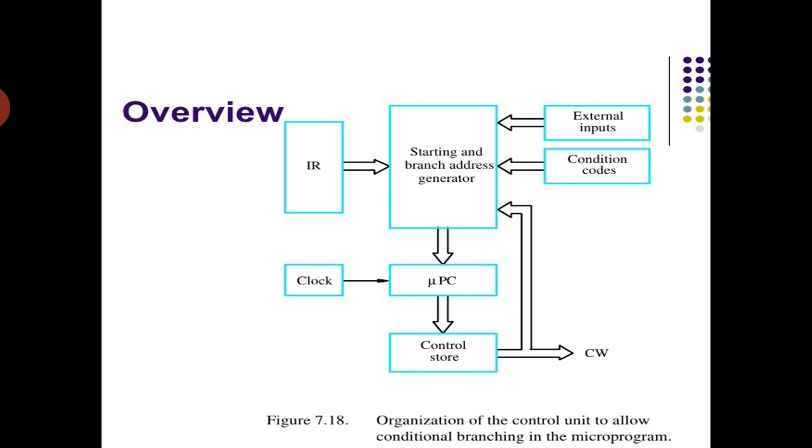The second one is when a branch micro instruction is encountered and the branch condition is satisfied, then the microprogram counter is loaded with the branch address.